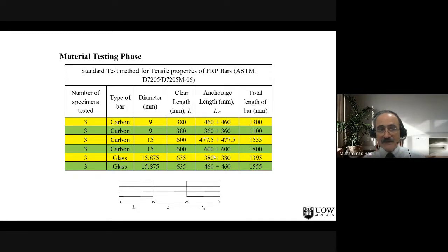Then on top of that, there are the anchorage lengths. So for those, we built steel tubes, we put the bar in, and then we bought expansive cement, put it in, left them for 3 days, not longer, and tested them. If it is longer, you will have problems.